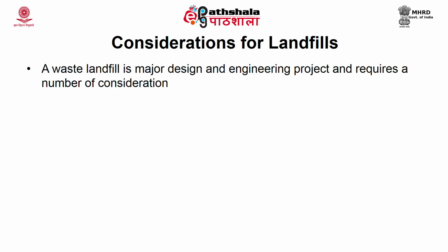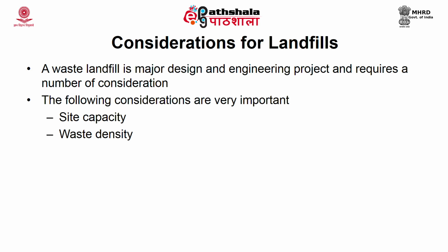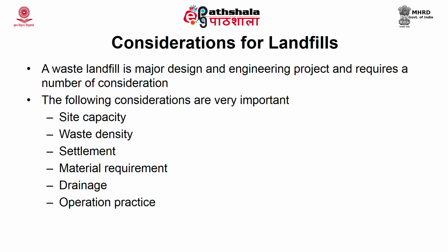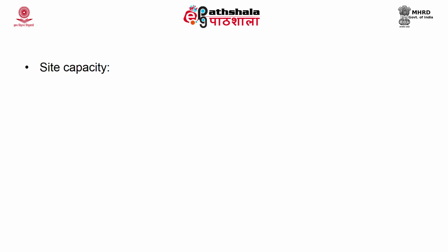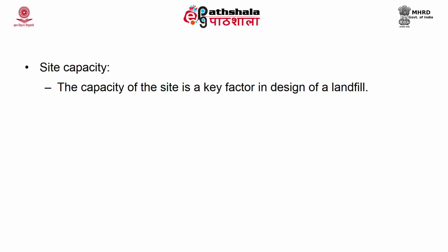Since it is an engineering structure, you should consider the following criteria. One is site selection, second is waste density, third is settlement, fourth is material requirement, fifth is drainage and operational practice. If you consider all these parameters, then the construction of a landfill will be smooth. Now, site capacity. The capacity is one important factor when you design a landfill. The landfill should be able to accommodate waste for almost 30 to 50 years.